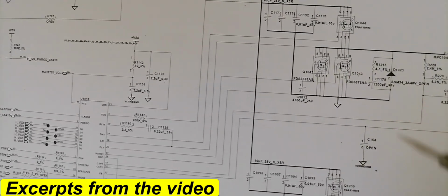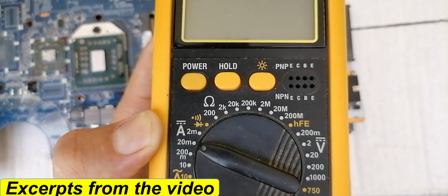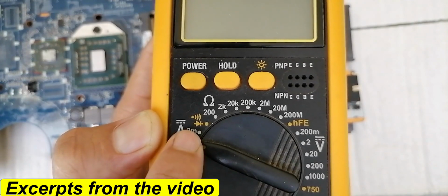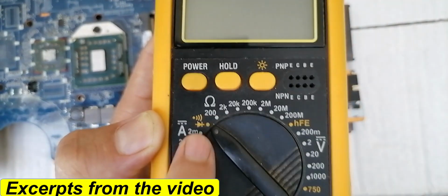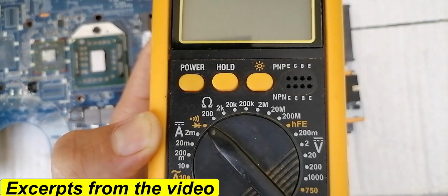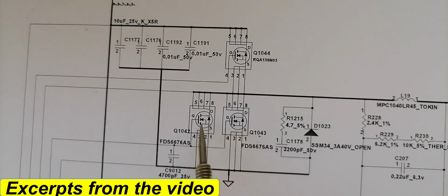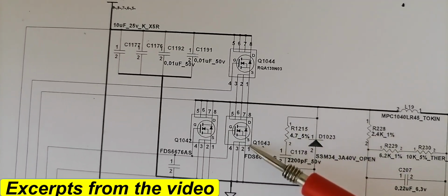We can even check the MOSFET using the multimeter. To check the MOSFET using the multimeter, we should always select the diode option. Why? Because simply the MOSFET contains a diode inside it. As you can see, this is the MOSFET, here we have the diode. Do you see the diode between drain and source?